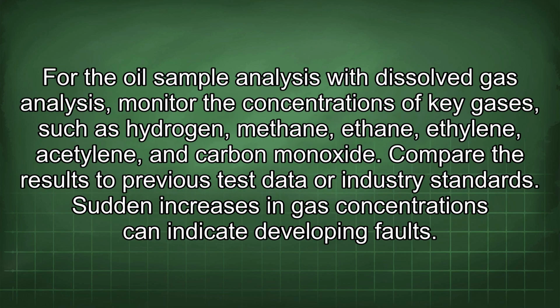For the oil sample analysis with dissolved gas analysis, monitor the concentrations of key gases such as hydrogen, methane, ethane, ethylene, acetylene, and carbon monoxide. Compare the results to previous test data or industry standards. Sudden increases in gas concentrations can indicate developing faults.